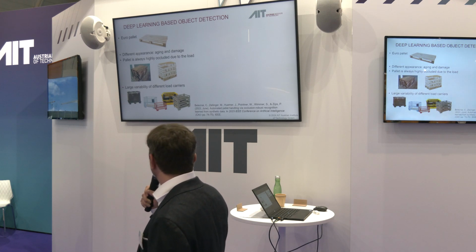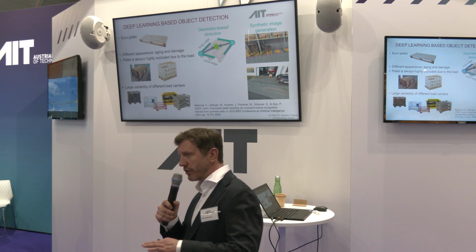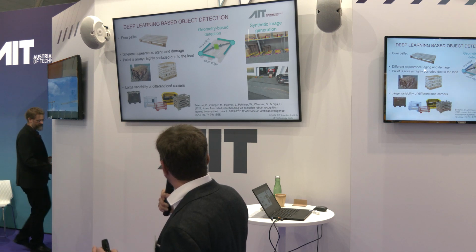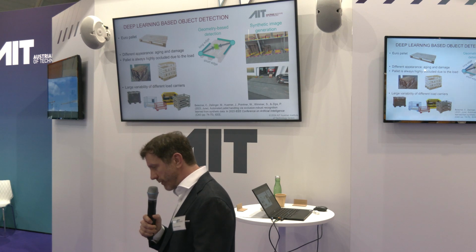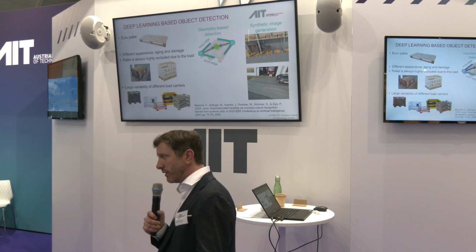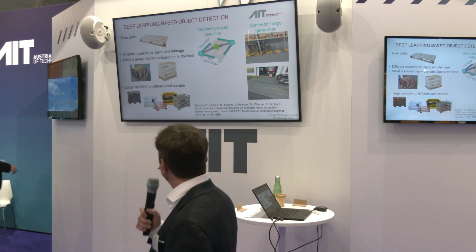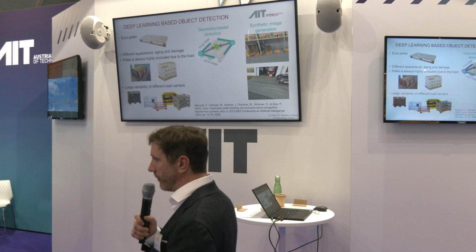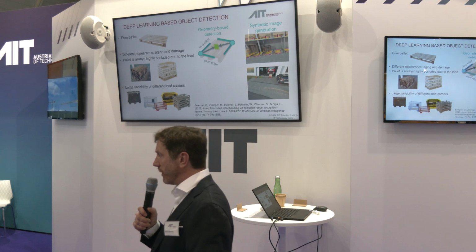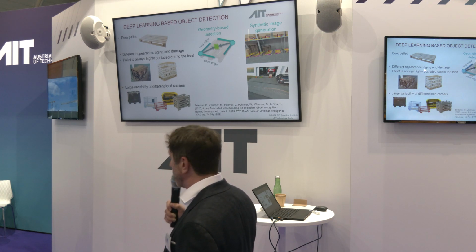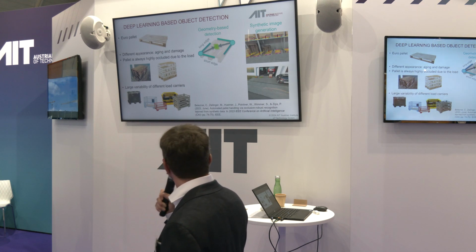that's what we did. And we did so by using only geometry-based detection features, which combine a bottom-up and a top-down approach by representing first geometric elements such as edges and corners, and then connecting them in the deep learning network itself to give a complete response for the entire entity of a pallet. So it's a bit similar, the network, if anybody knows, to CenterNet from the voting mechanism, but it has a lot of other features for the edge detection, for example.